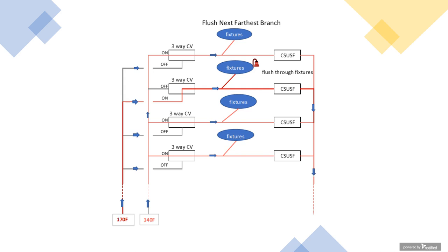Now, the other thing, again, like with the first system, is if there has been a Legionella event detected, and it was, say in this case, branch 4 that was determined to have very high bacteria count, again, with your control, you can automatically go to branch number 4 and thermally disinfect branch number 4 while keeping everything else in service. And you could do that again with practice, with the right rehearsals. You could do that again within an hour. So very powerful.